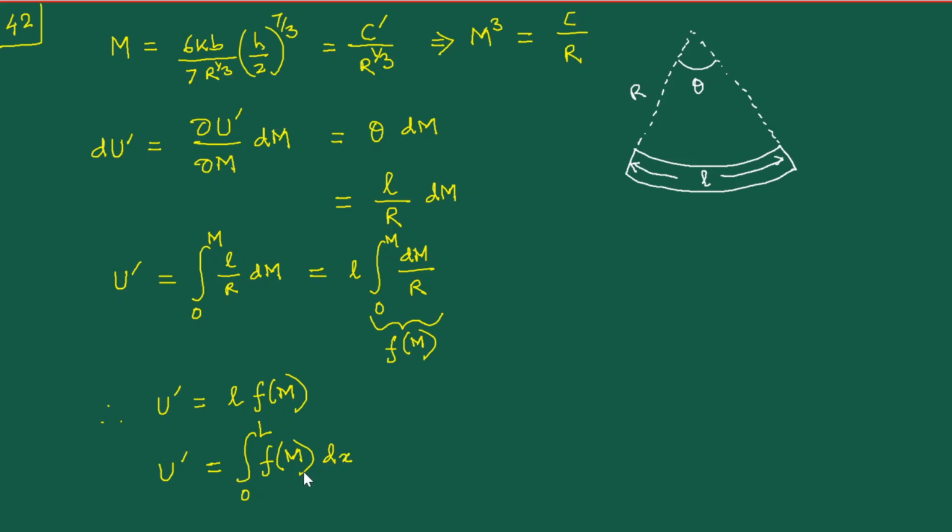Now with this understanding, what can we do regarding the deflection? Because you see, what we have basically managed to do through these rather arbitrary steps is to write an expression for the complementary energy as some function of the m, integrated over the entire length. So this is the counterpart of what we had written earlier for the strain energy as m square by twice EI dx integrated from 0 to L. That is what we are trying to get at.